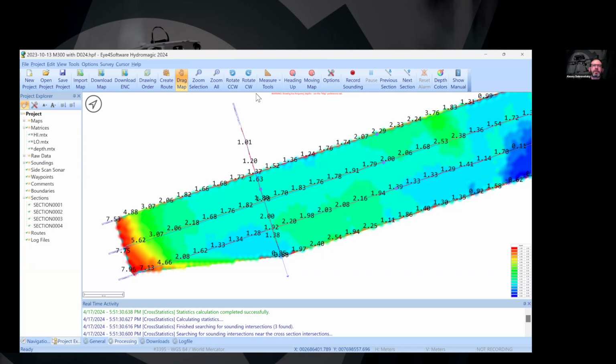Next, low-frequency GPR mounted on the drone will have quite a deep dead zone below the water surface, because water is almost an excellent reflector for electromagnetic waves, and a large portion of the energy of every radar impulse will bounce between the water surface and the drone body.